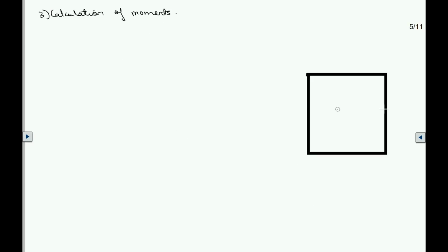As you can see, I have drawn a figure of the S1 slab. Now the S1 slab is continuous on this side. It means that the shorter edge of the slab is continuous, and all the 3 other edges are discontinuous.